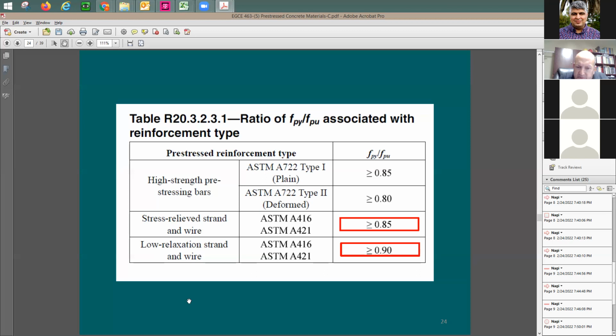Is this important to me? All I care about for now, this is my understanding, is 270, 189, 150. These are the three numbers I need to memorize, as long as I'm doing pre-stress. Three numbers again: 270, 189, 150. Some people would say 270, 190. I'm okay with that. I mean, 189 versus 190 does not make a big difference, right?